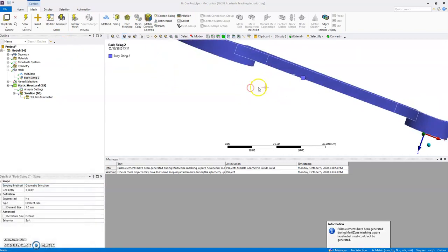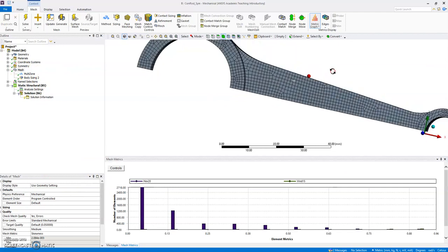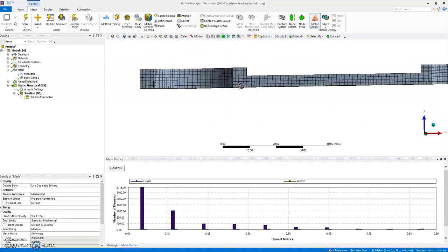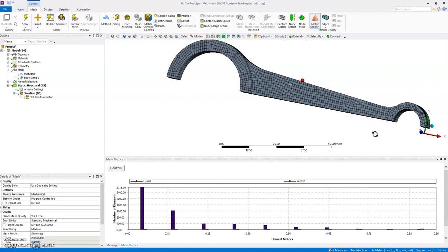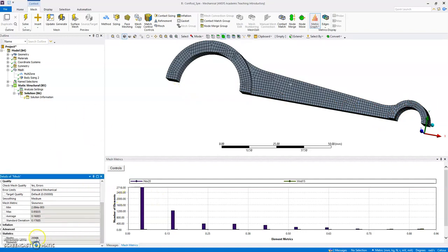So yeah, still prisms, and I think I've got prisms all along there. Let's check the mesh. Visually, I can see that's starting to be to my taste. So nice and regular here. Not too sure about that bit here, but that's what it is. 4 elements there. Maybe not enough here. I would prefer to have at least 4, so I might need to apply a local refinement sizing, perhaps on that side. Let's check the number of elements. This is something I could run on the student edition of ANSYS, which has a 32K maximum. So I'm quite pleased with that mesh.